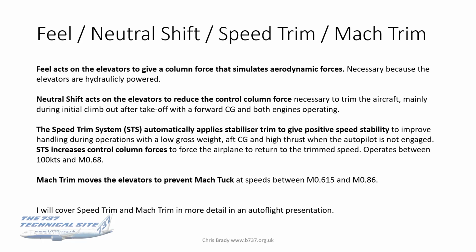And finally, Mach trim. This moves the elevators to prevent Mach tuck. And this is active between 0.615 and 0.86. Once again, let me just say that I'll cover speed trim and Mach trim in more detail in a subsequent presentation. But that right there, that's your summary of those different factors.